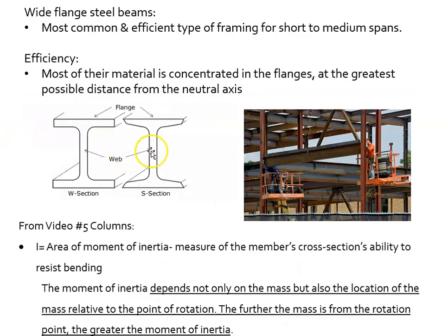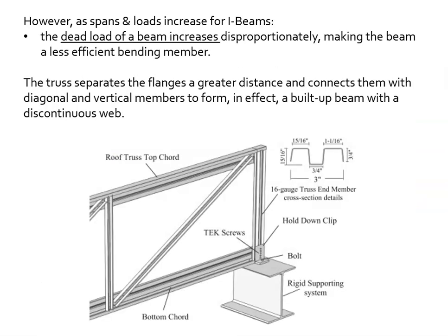All right, so steel beams could be built up of several different pieces. Smaller ones are typically hot rolled right from the mill as is, but larger girders are built up with several different pieces, often stiffeners and plates within. So steel beams can be built up, and we will see that when we dig deeper into steel.